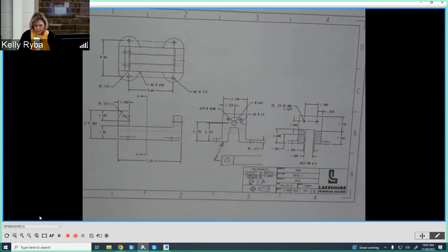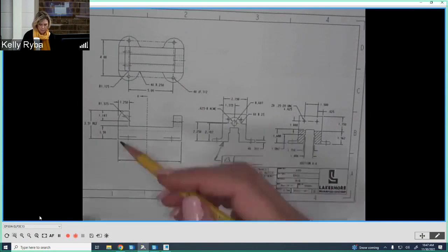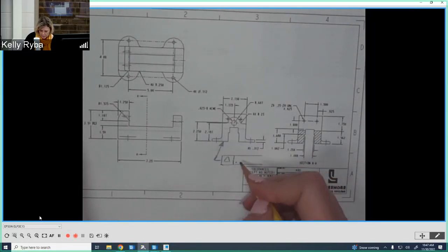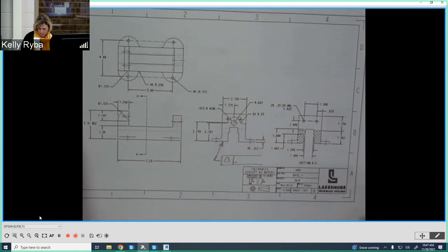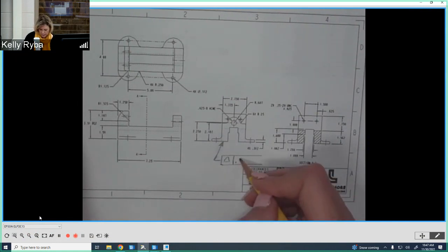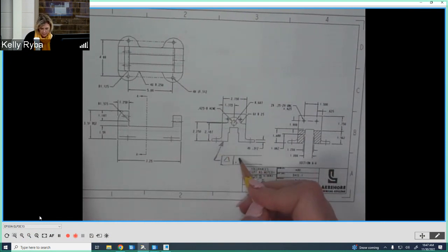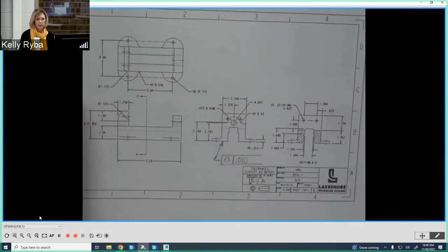And right now, if we look here, our tolerance for machined surfaces is going to be plus or minus 20 thousandths right now, because this is a 2-place decimal to the bottom. So what we'll do is we'll add, we're going to say, okay, we need that to be a refinement of more than 40 thousandths. So we're going to say, okay, how about we'll put a flatness on there. We'll make it nice and flat, all coplanar, and that's going to be something less than 40 thousandths. I'm going to say 10 thousandths. Okay, we don't want to go crazy.